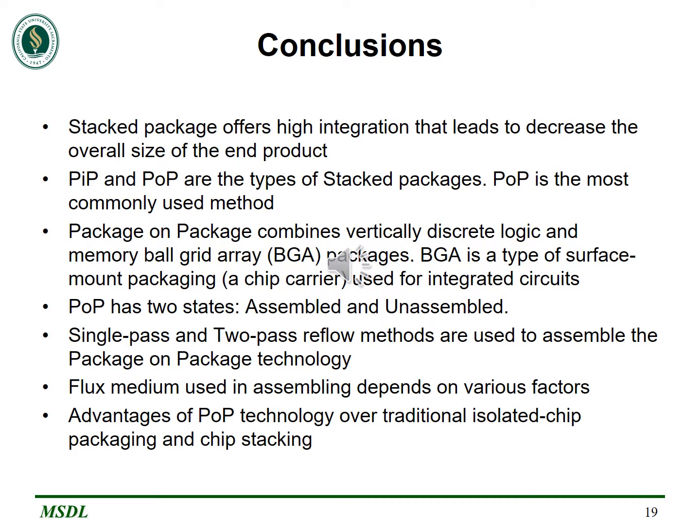Single pass and two pass reflow are the methods used for assembling the package on package semiconductor technology. And the flux medium, which is used for combining the top package and bottom package in the package on package semiconductor technology, depends on various factors. Then we discussed various advantages of using package on package semiconductor technology over traditional isolated chip packaging and chip stacking. That completes my presentation on package on package semiconductor technology.